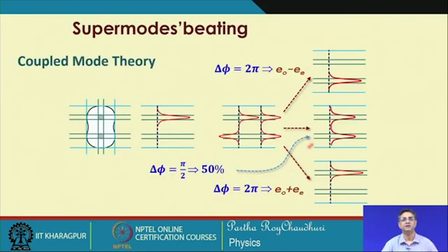So, to understand the same thing in the case of an optical fiber, you have a core here, you have another core here, and light is launched into this waveguide. At z equal to 0, we consider that this mode which is in the first fiber is a combination of the two lowest order super modes, that is, the normal modes of the total structure.